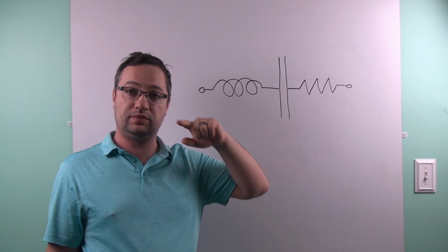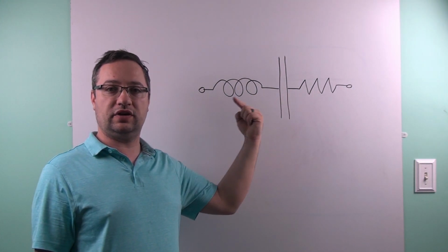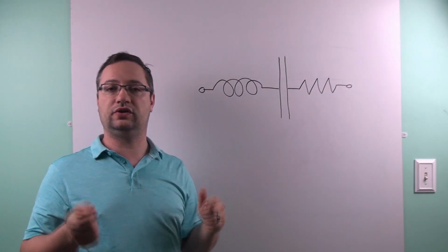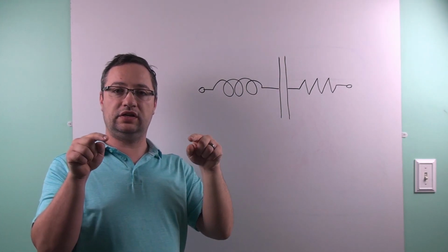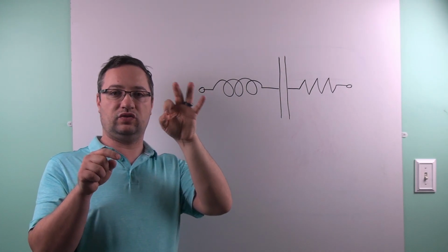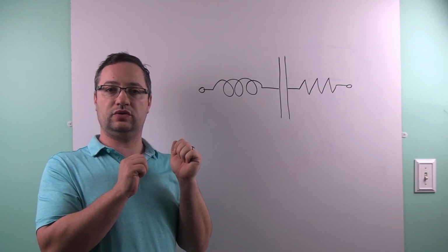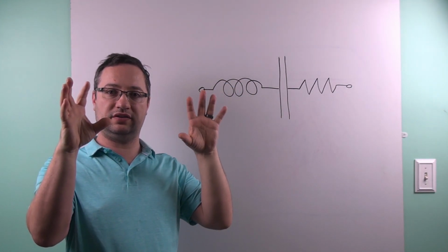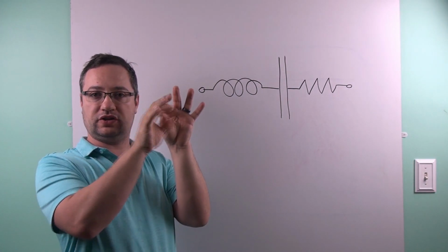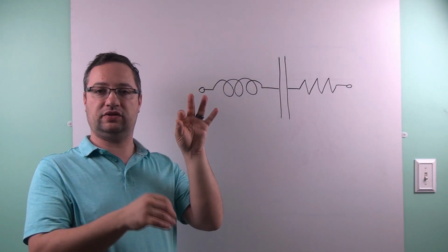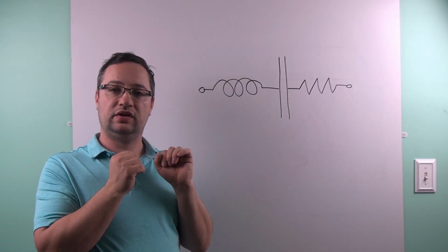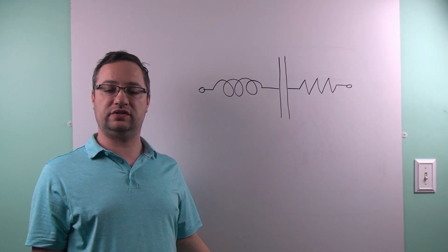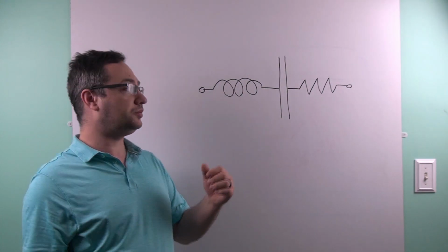Where does this resistance come from? It comes from the fact that the capacitor has leads on it. Something has to attach to the capacitor and then to the circuit board or whatever you're attaching to. And those leads are not the same thickness or width as the actual plates of the capacitor, so what you get is sort of a bottleneck effect. As the charge is leaving the plates, the charge has to funnel down into a much smaller cross-sectional area to then leave the capacitor, and so you get some kind of resistance. Depending on the physical construction of the capacitor, that resistance can be high or low.